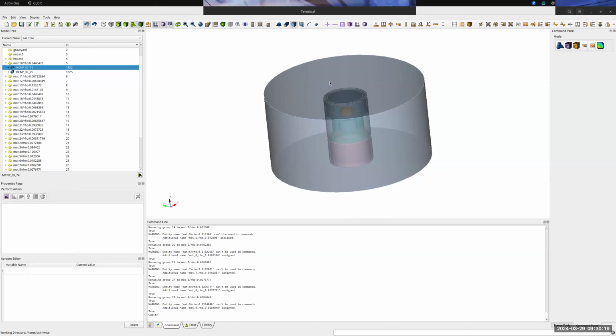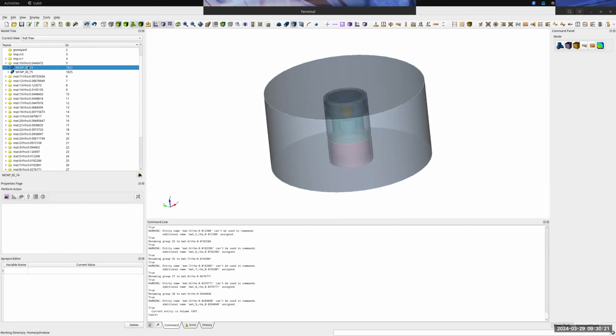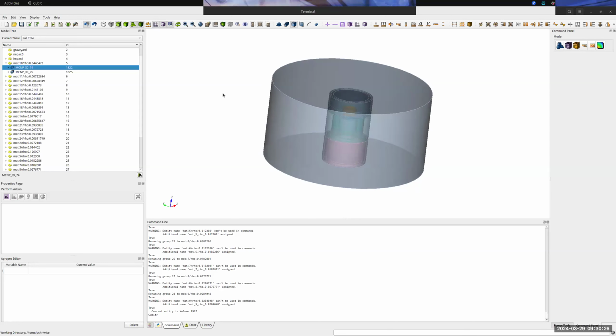Here we see one that's somewhat deep in the core. Oops. For this first material assignment, material 10, I could create a mesh block for this, add the volume, and then create a new material here as well, and assign that to the block. But much more preferable would simply be to leverage another Python script to do this. And so that's exactly what we're going to do today.